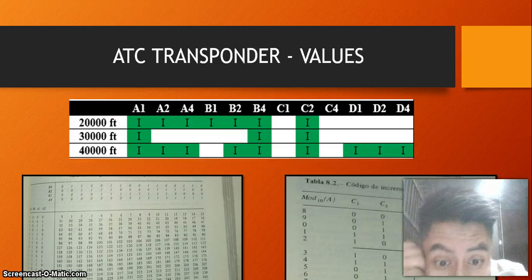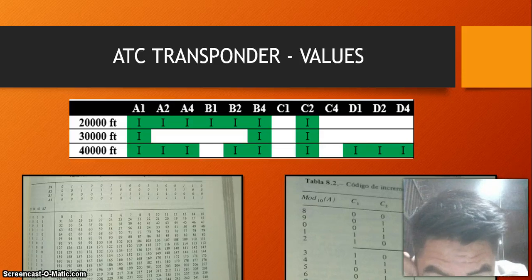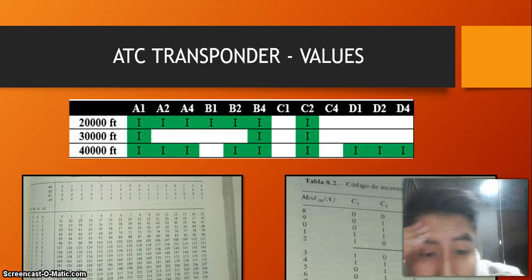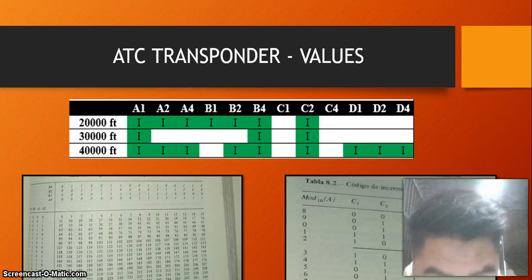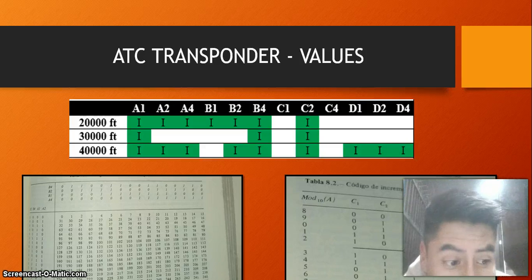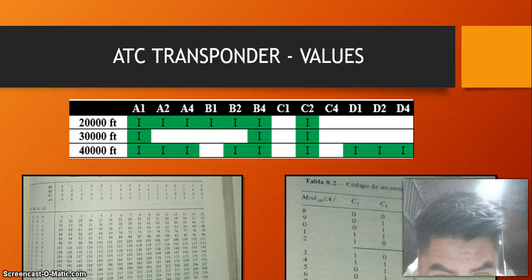For Mode C, which indicates the altitude at which an aircraft is located, the selector knob must be changed to the desired type of operation. In this case, we begin with the following encoder, in which the different altitudes were inserted in gray code.